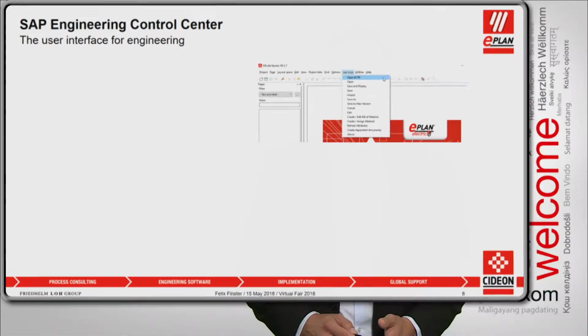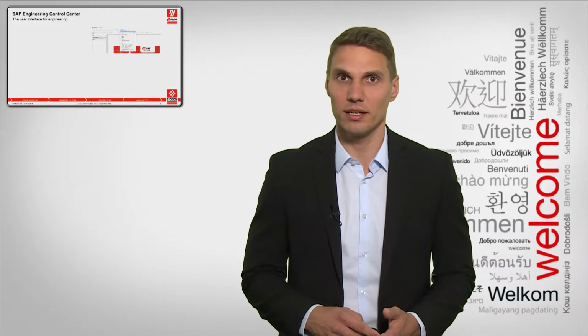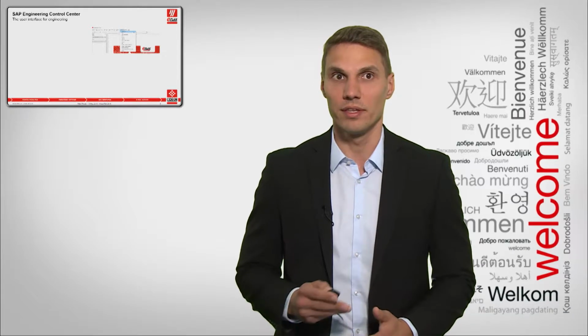And this enables you to execute the most important functionality in terms of data management here. And maybe if you look closely enough, then you can see that for the E-plan, you have, for example, one entry that lets you derive bill of materials. Coming back to the point in the beginning, if you're struggling with handing over bill of material information from E-plan into the ERP landscape, then this is exactly something that could really help you.